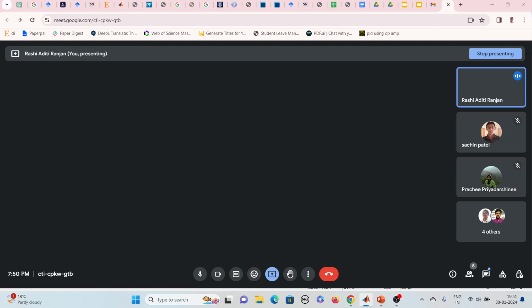Okay. Then I have taken t. I have defined it in square brackets, 0 to 0.01 to 100. Now what does it do? Let me take an example. T is equal to 0 to 0.01 to, let me say 1. Or maybe I'll just use 1 to 10. What did it do? So T is an array now with the values 0 to 10 with a difference of 1.